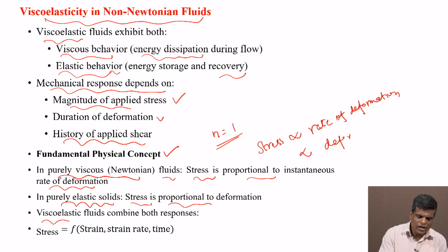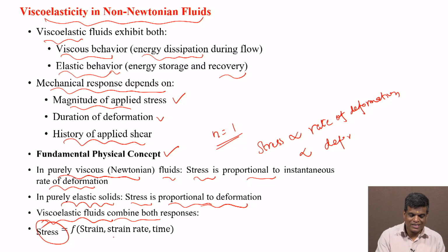So, the viscoelastic fluid combines both responses. The stress is a function of strain, the strain rate, which is the rate of deformation, and of course time is also a factor here. So, in viscoelasticity, the stress is a function of strain, strain rate, and time.